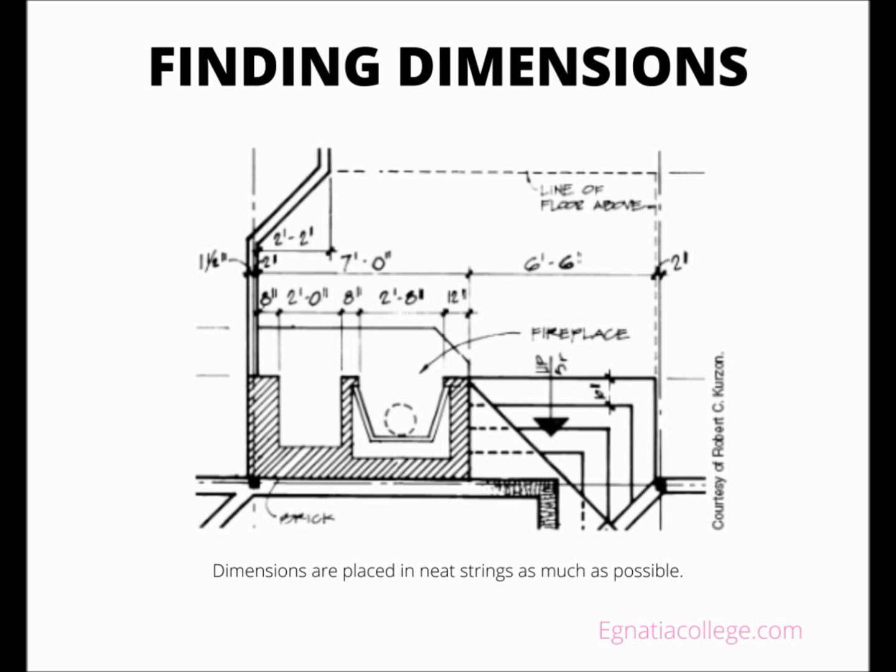This house includes an angled wall. The length of such walls can be accurately found by trigonometry. However, the accuracy obtained by measuring with an architect's scale should be adequate for normal estimating. As each wall is laid out, the plates are cut to length, and the positions of all openings and intersecting walls are marked. The wall frame is usually assembled flat on the deck. Its position is marked on the deck with a chalk line, then the assembly is tipped up and slid into